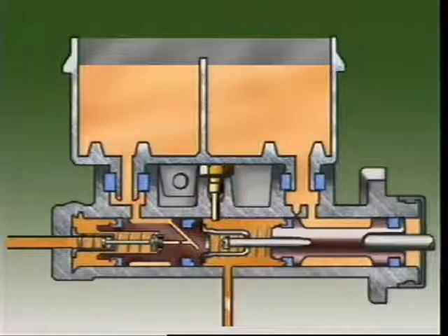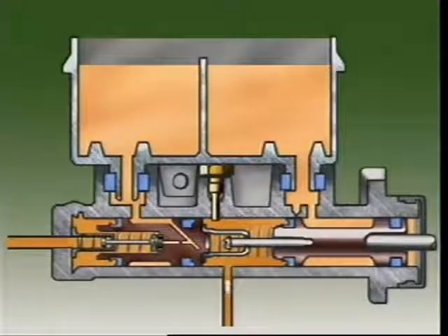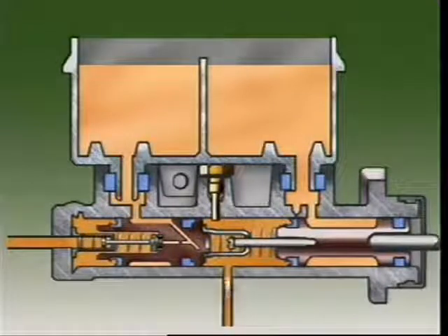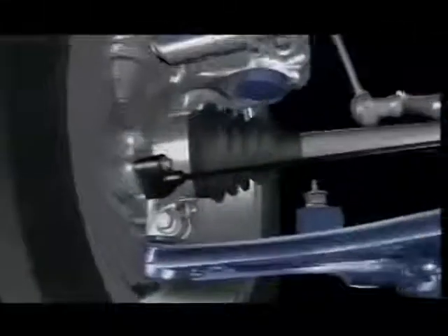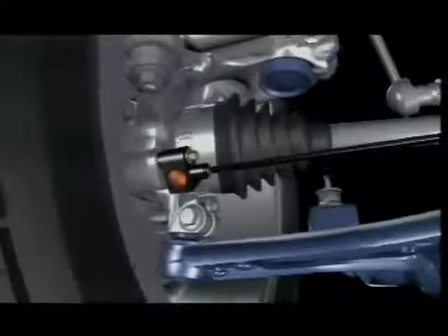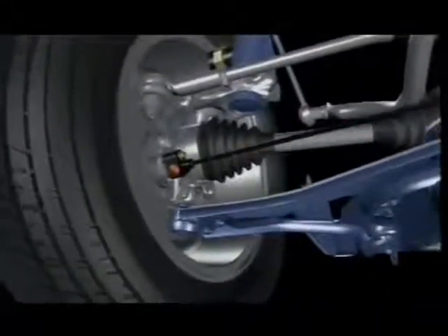If fluid is returned from the rear brake circuit, the secondary and primary pistons tend to be forced apart. The amount of fluid that returns to the master cylinder is determined by the degree of anti-lock braking control. With approximately 4 to 6 ABS control cycles per second, the rapid changes in pressure cause pulsations that can be felt by the driver at the brake pedal.